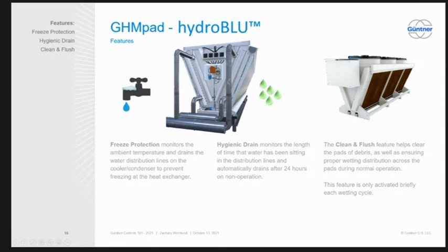So if you have a temperature sensor behind the pad, that's when you can do the floating set point. It's not going to look at the temperature humidity sensor that's on the actual unit. That's usually installed on the opposite side of the control panel, so it'd probably be right around here. Control panel's here, you have your Belimo valve and water meter and stuff, that would be over here.